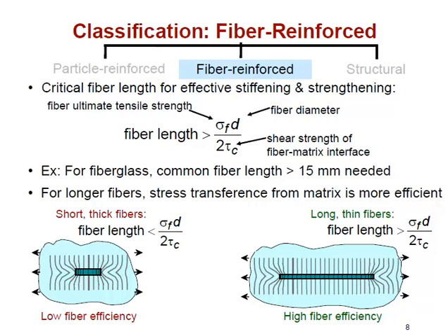Additionally, they will tend to be the things that make your composite maybe a little bit more dense, and so you want to use them sparingly. On the other hand, you're using them for a reason. You need them to do their job. So volume fraction of fiber and fiber length are two different independent variables that you typically can choose from.